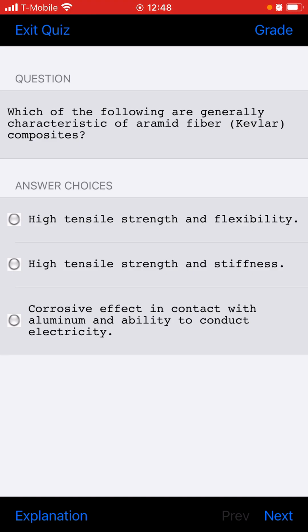Which statement is true regarding inspection of a stress skin metal wing assembly known to have been critically loaded? If genuine rivet tipping has occurred, groups of consecutive rivet heads will be tipped in the same direction.